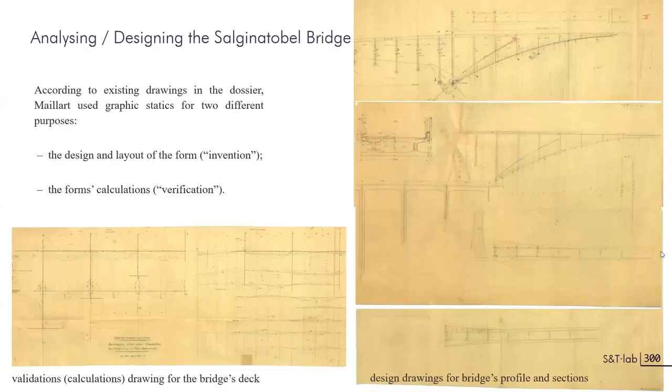These are working drawings showing thrust lines, funicular polygons, and a force polygon that will be used with several successive drawings to define the line of the arch.